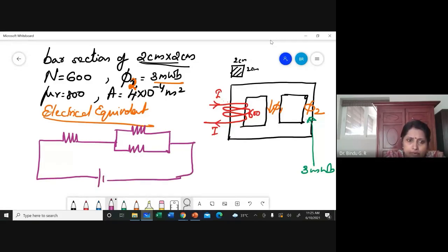Okay, this is my V, R, R1, R2. Or to put it in the magnetizing form, magnetic circuit form, instead of V I have MMF, Ni. This is S, this is S1, this is S2. Similarly, I have this current as I. This is I1, this is I2, current I.